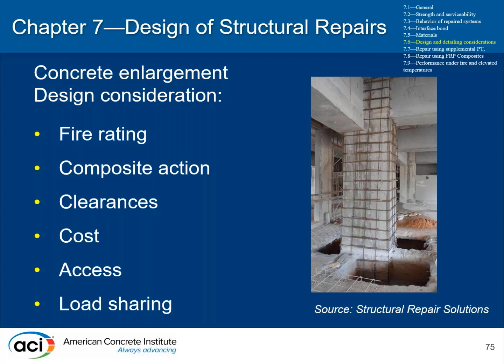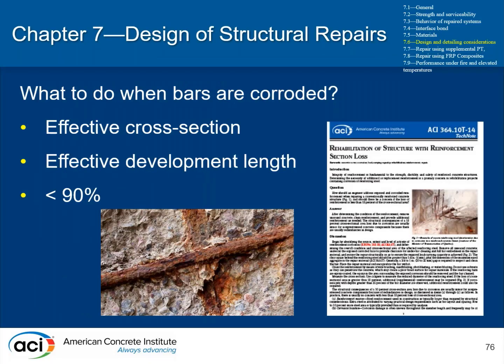As with all repairs or repair methodologies, cost and access become critical, as well as load sharing. And again, we talked a little bit about that with regards to columns, but making sure that the loads are getting into the repair areas or into the strengthened areas to adequately share them, as is evaluated and required by the analysis.